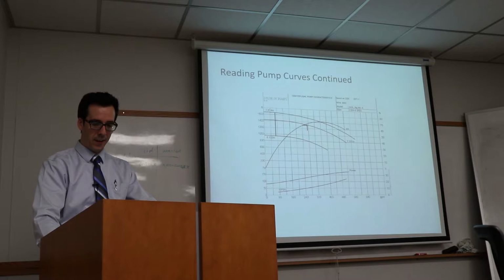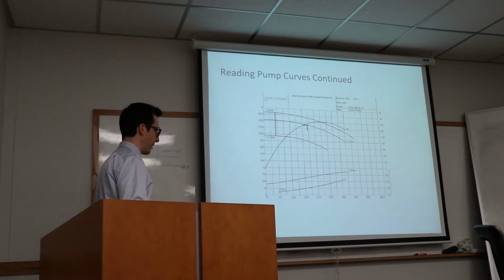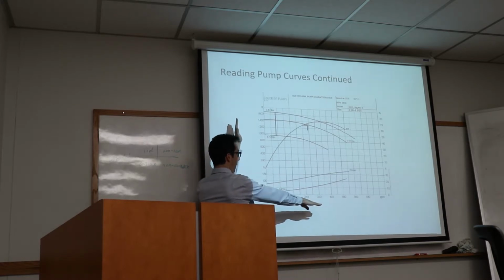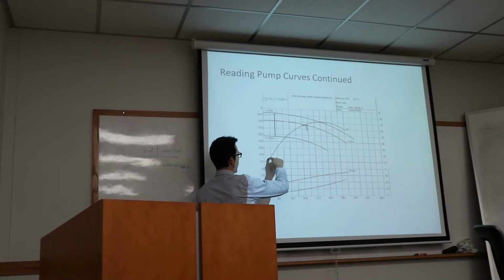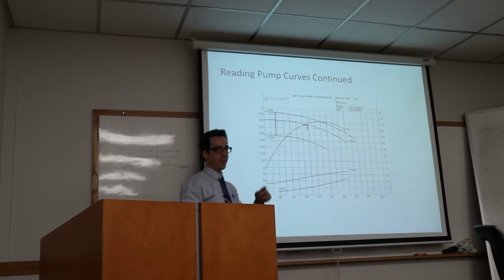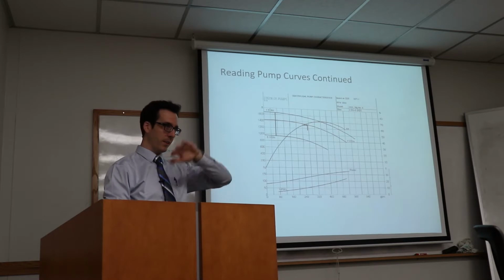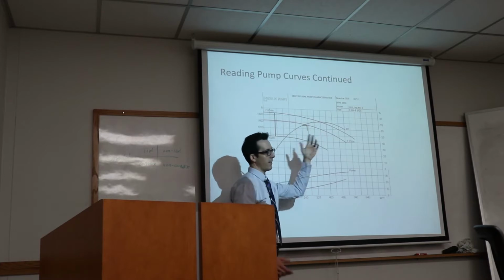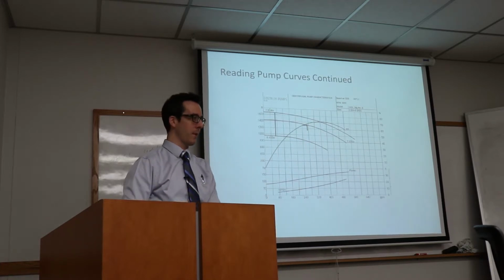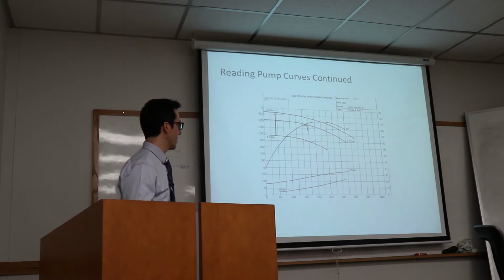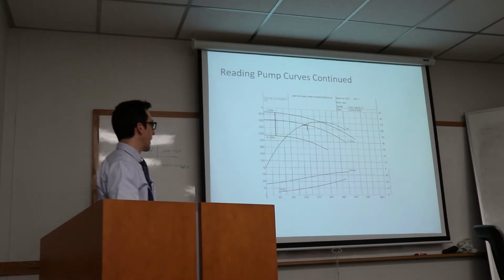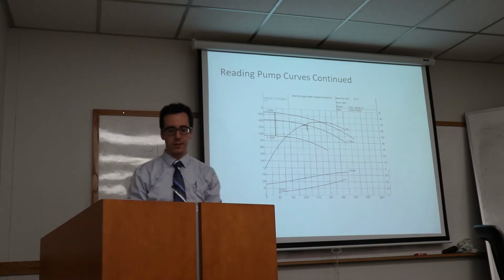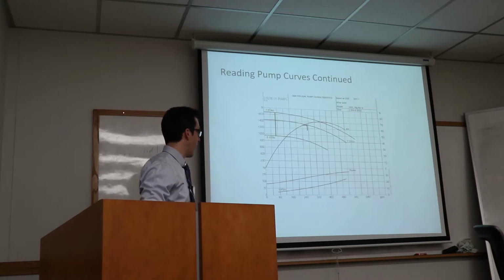Okay, so here's a different kind of pump curve, and this time I won't reveal the answer. We still have our flow and our head. The only difference here is that this is the efficiency curve, so it's either these U-shaped zones or it's an arc, okay? And this little notch, by the way, represents the design point that some engineer specified for a particular project. So we'll ignore that for now. And again, a range of impellers cover this range of flow conditions.